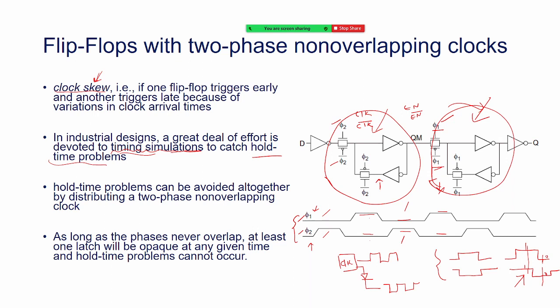And any significance about that? What do we mean by level trigger and edge trigger? We just saw that. But what happens because of that, and why are they different? The question is the difference between flip-flop and D-latch. That's my question, and she answered: flip flops are edge triggered and latches are level triggered. So I said okay, and I want to know from you people, please elaborate. Latches are level triggered and flip flops are edge triggered, but because of that, what are we understanding and what's the meaning of that?